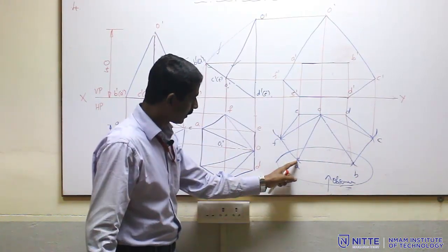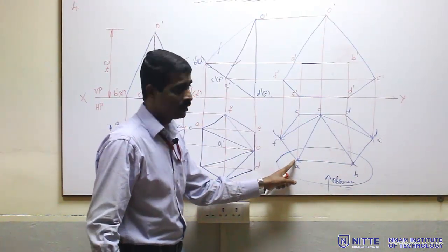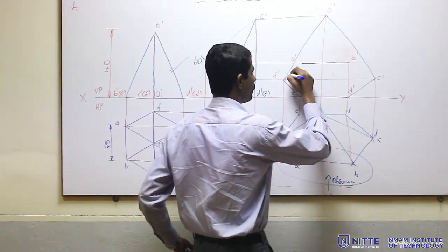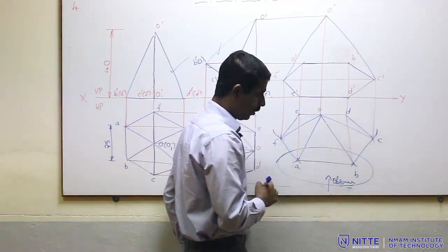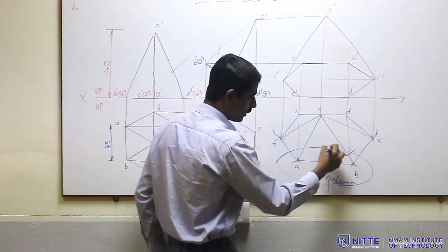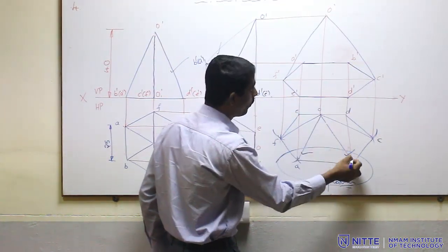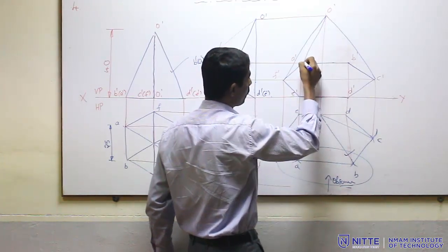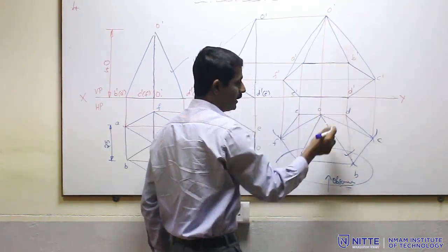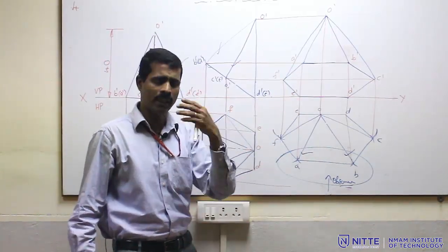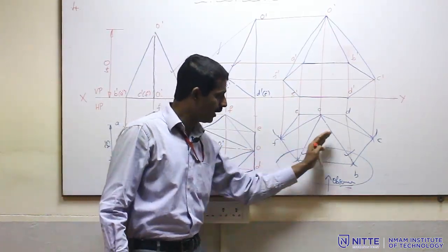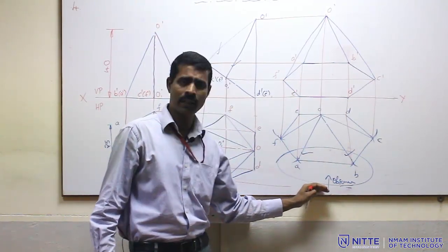Okay. Then next, AF is partly nearer. So, definitely it is visible. BC is definitely visible. Okay. These two lines are nothing but OA and OB, that is also visible. So, this is how I can understand which are the visible edges in the final front view in any solid problem. Okay. Look at the region nearer to the observer.